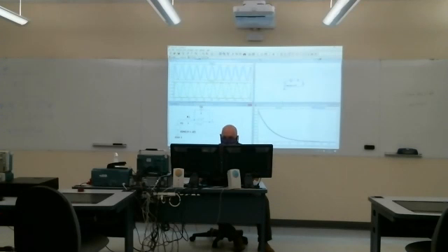Okay. So there should be a 90-degree phase shift between the sine and the cosine. Well, if you'll notice here, the output actually starts at its peak, like a cosine, or the sine here starts at 0. So it looks like it has the right phase relationship, that the output is the integral of the input.